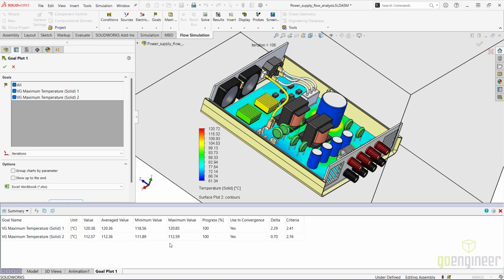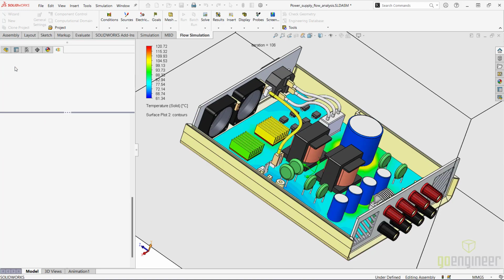If I were tackling this project in real life, we would probably have to reconsider the whole cooling design if we plan on running this electronics box in these harsh environment conditions, right? So we can see here that the 2 transformer components are pretty much blocking the airflow to that rightmost heatsink, just to start. So let me close this out.